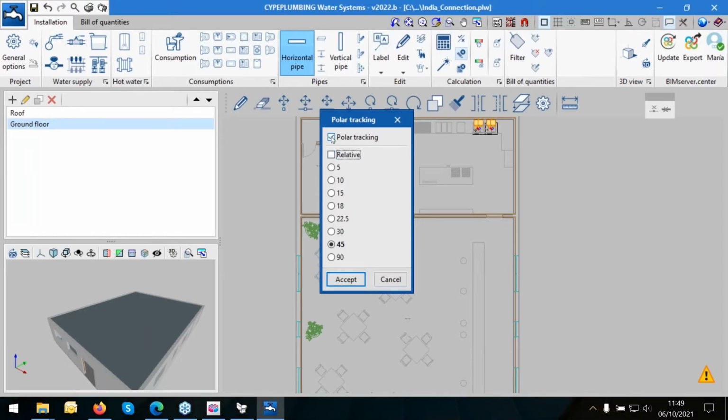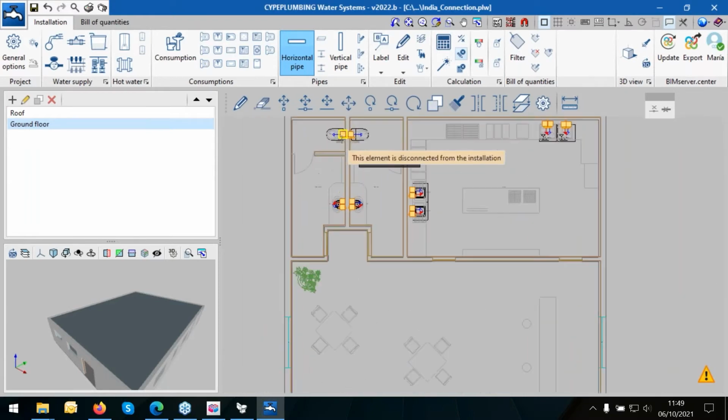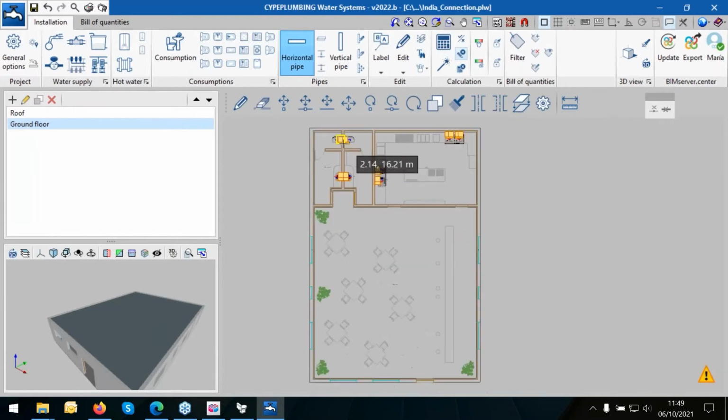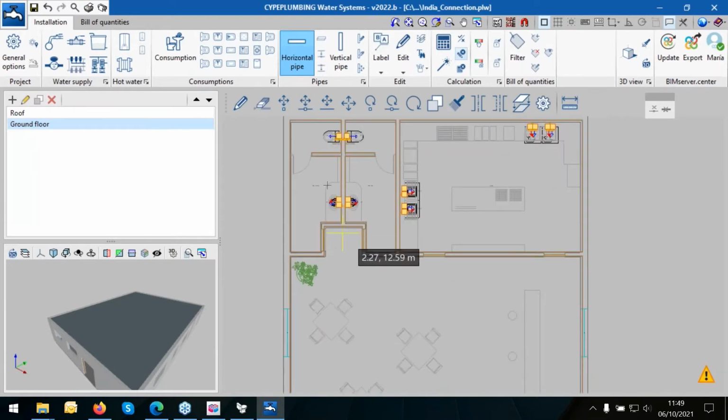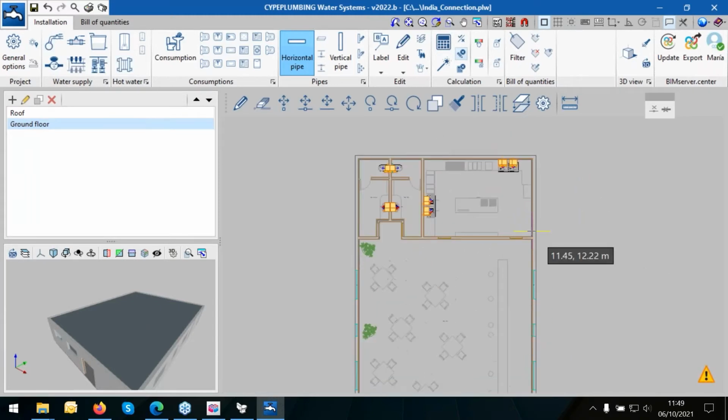This will be, of course, sorry, in the sanitary systems. In the water systems it is more open. Let's do this. We could start from the elements. When we are talking about water systems, we don't need to use a certain direction. We could do as we prefer, from the supply connection point and then go to the consumptions, or the other way. In my case, I think I prefer from the supply connection point. I will do that.